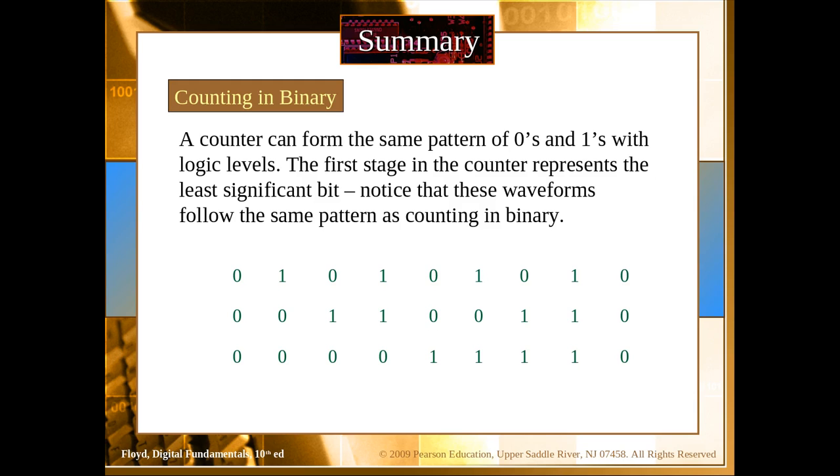Since we have seen that flip-flops could be used as frequency dividers, the only thing that we need to do is use one flip-flop to divide the frequency in half, so that every other flip-flop would divide the frequency in half. That would in turn change the bits from 0 to 1 or 1 to 0 after a certain number of clocks, depending upon its position.